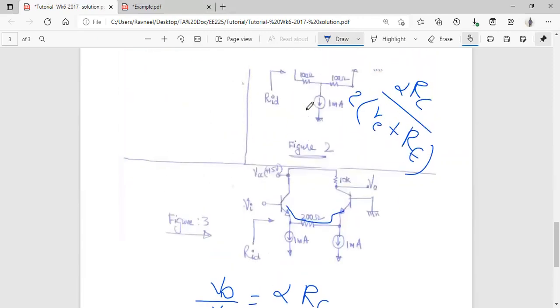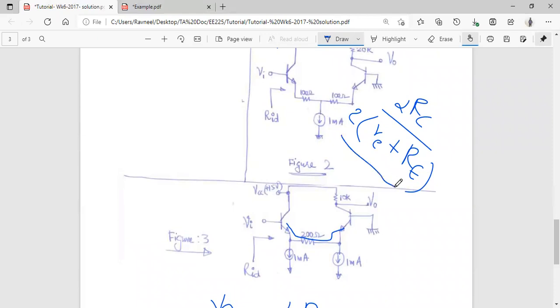So in this particular case, we use this particular formula, isn't it? In that case, you can see over here, it was 1 RE, right? It was again the resistance from here till here. So there was a small RE across this particular BJT, across B and E. There was a small RE present due to this particular BJT over here, right?